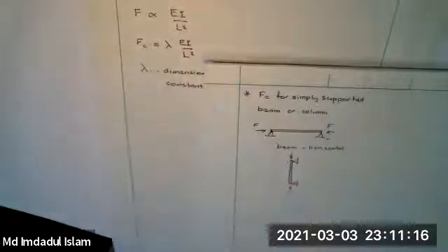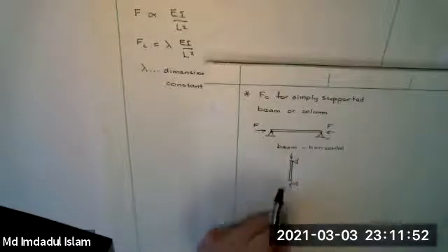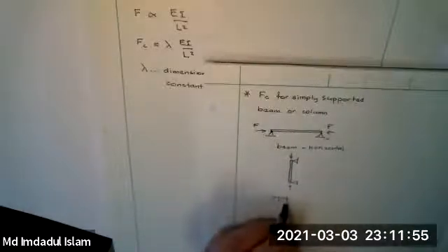In that case, if you took them in the elastic region, you'd hardly see any deflections. But once you started to yield, then they'd squash. And yielding in the plastic flow, the material essentially flows incompressibly. So if you shorten it, then it's going to get wider. It may not do that right where the grips are, because it may be crimped there, but elsewhere it will. And that's a competing mechanism with buckling, when you can have yielding, which occurs for short, stubby columns. This is a column, it's vertical.